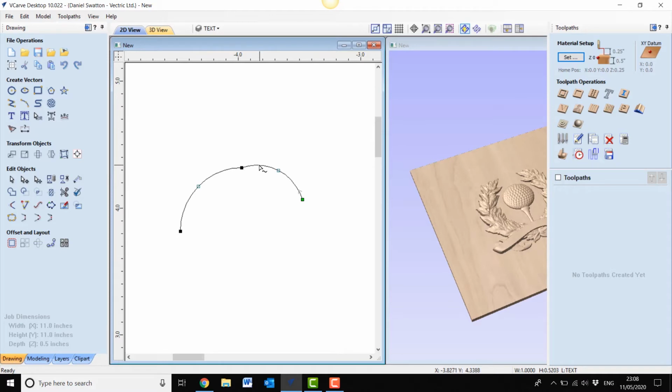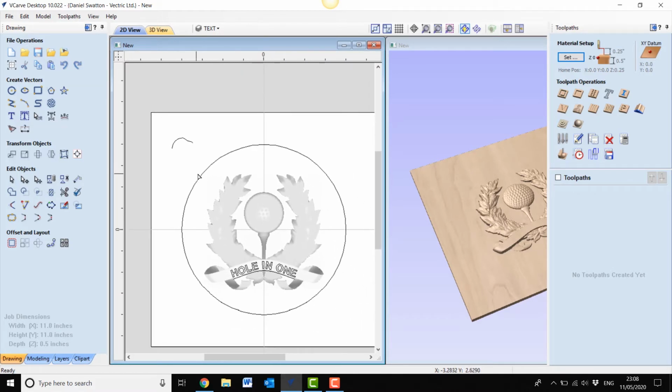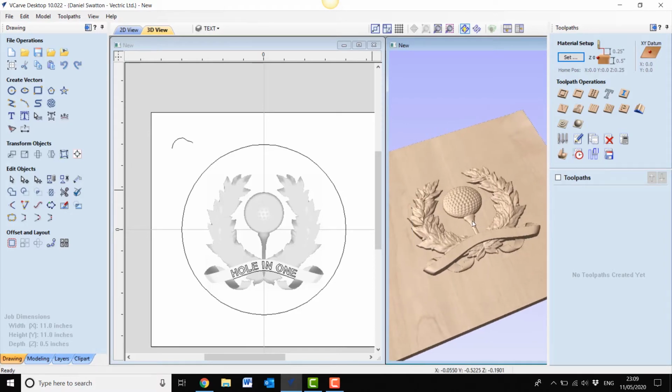I'm just going to change this to Bezier and make sure that it's nice and flat at the top. And I'm going to add in an extra point here with I on the keyboard, and manipulate this to create a nice shape, which will look a nice form when we create the molding. So we can zoom out now, and we can see the outer perimeter and the cross-sectional shape. With this, I'm going to come straight across now and look at the actual toolpath that will generate.